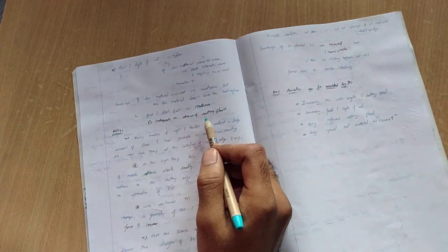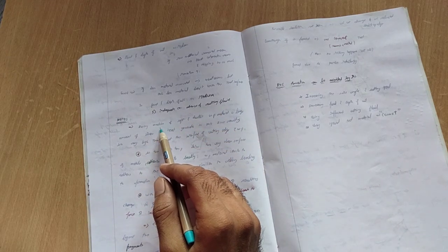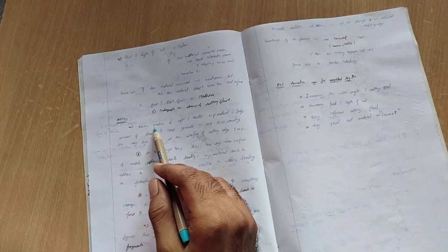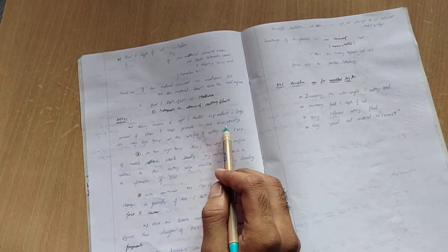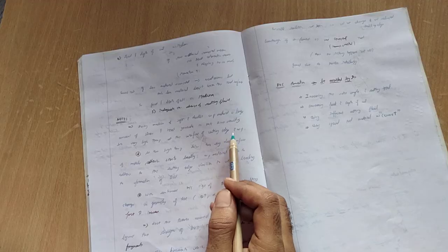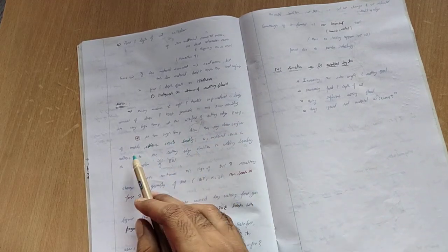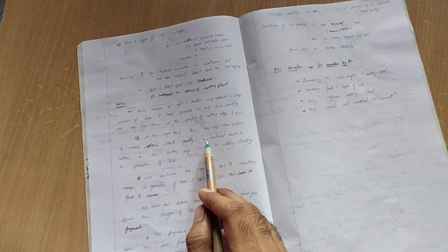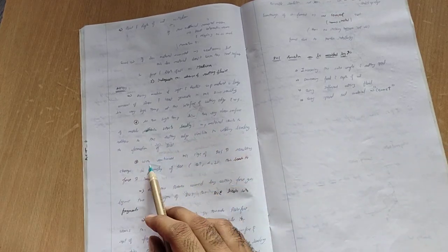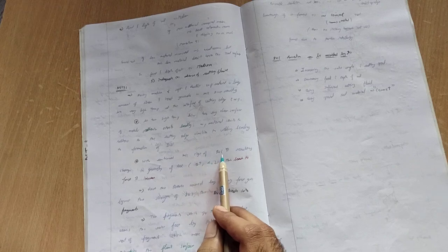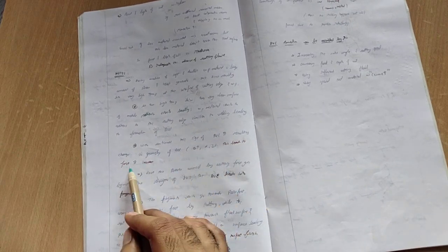Next, inadequate or absent cutting fluid. During machining of a soft and ductile workpiece, a large amount of stress and heat is generated in the workpiece, so there is very high temperature at the cutting edge. At very high temperature, the surface is very clean and adhesion definitely starts. The workpiece starts to adhere to the cutting edge, similar to a welding action, forming the built-up edge. As machining continues, the built-up edge increases, changing the tool geometry, and this leads to increased force.